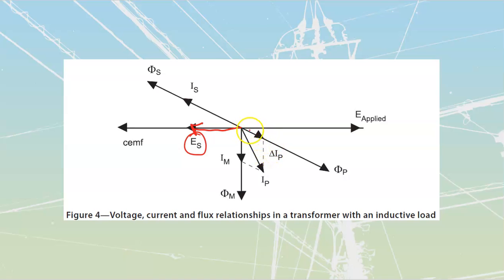So we see that we are going to have my primary current over here, which is made up of the reflection of this, but then this gets added onto the magnetizing current that we originally had down there below. The first graph we looked at showed magnetizing current, then we added on the primary current and they form a new vector sum, which is this one over here. That's going to be my actual primary current.